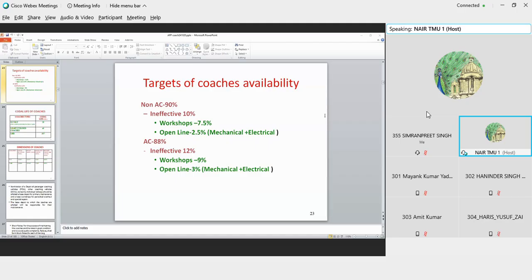As you understand, a diesel loco is a 6,000 horsepower locomotive. You convert it into megawatt, and you see how many panels would be required. The train is moving. Under no circumstance can you put so many panels on top of the coach body that it can give you power for propulsion also. So directly it cannot be. Indirectly, if you put a large number of panels and then take the electricity through the catenary, yes, it can be done, and it is being done. CNW stands for carriage and wagon.